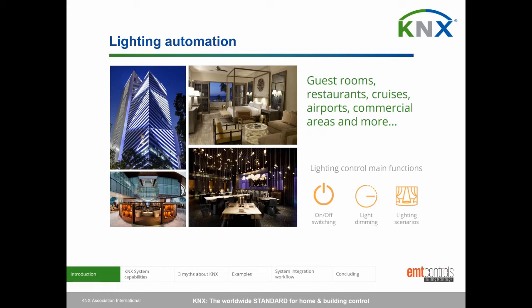For this purpose, a wide spectrum of KNX devices are used. Wall panels, switches, and sensors as elements of the user interface for the system. Dimmers and actuators as elements of electrical control of the light itself. Gateways, interfaces, converters, repeaters, couplers, and power supplies for service purposes, and the controllers, smart devices that can perform control of the system at a higher level.